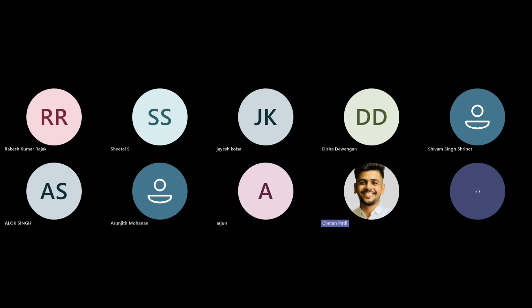Yeah, you can extract the forces as well. If you right click on the forces that you have with you, actually my screen got lagged a little bit here. I don't know what happened with the screen. You can right click on any one of the joints that you have created, drag and drop it into the solution, and create the force reactions on that joint.